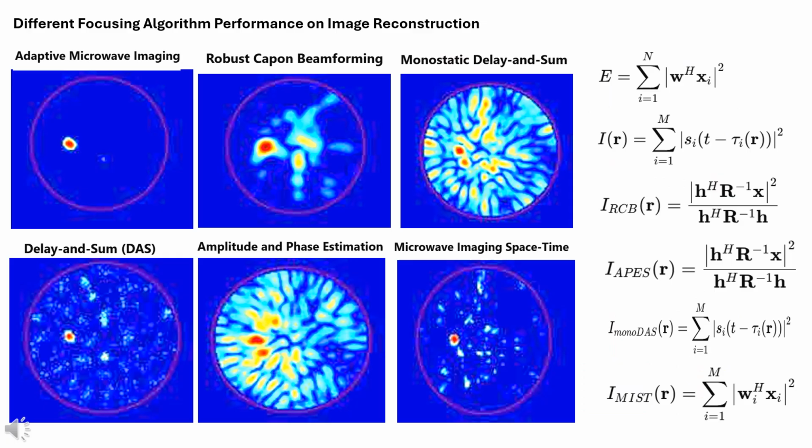After time aligning the signals from multiple antennas, the signals are summed together to enhance the signal coming from the desired location, which is known as the focusing algorithm of coherent integration. The goal is to enhance the response from the desired location and suppress noise and interference from other areas. The process essentially reinforces signals that come from the focal point, leading to a clearer image.